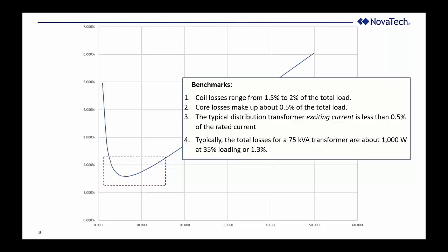Well, remember that 2 or 5 or 10% accuracy in measuring the losses is 2 or 5 or 10% of the 2% contribution to the total load. So even if your calculation of the total losses is off by a fairly large number like 5%, that's still 5% of 2%, which makes it worth calculating. You can't just assume that the accuracy of the losses translates into the accuracy of the measurement of power.